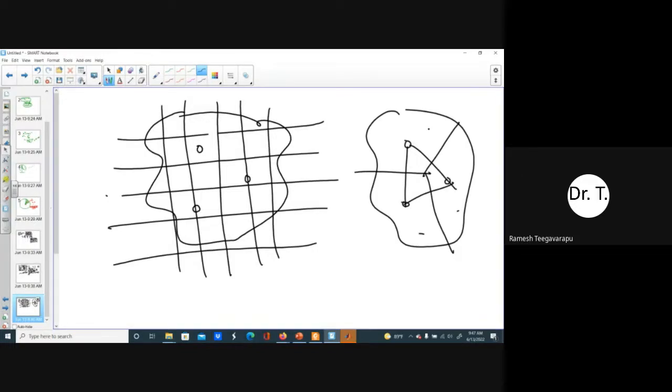And most of the flash flood forecasting models, especially in different parts of the United States and the world, use some kind of gridded rainfall product. In the US, we use S-band radars. They have strong strength and a range of 230 kilometers. Because of their strength, the attenuation, the reduction in the strength of the signal, is less. But as you go further and further from the radar site, your accuracy might be affected. Therefore, we use multiple radars where there is an overlap.